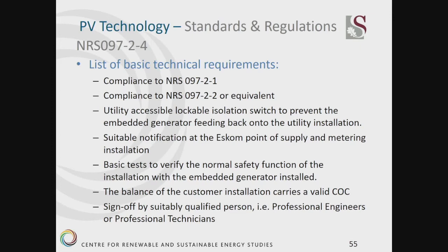Then basic tests need to be done to verify the normal safety functioning of the installation and the embedded generator installed, and that the balance of the customer installation carries a valid certificate of compliance. And then sign off by a suitably qualified person needs to be done, and currently this is a professional engineer or professional technician that can sign off on an installation.